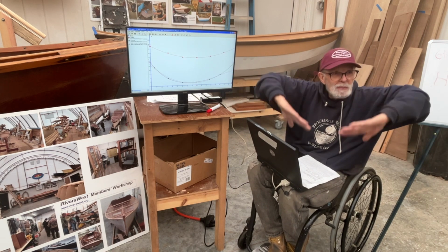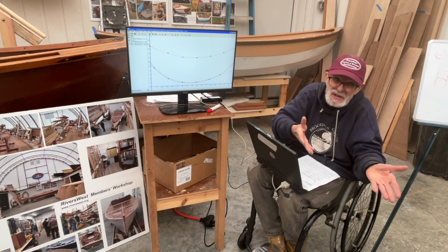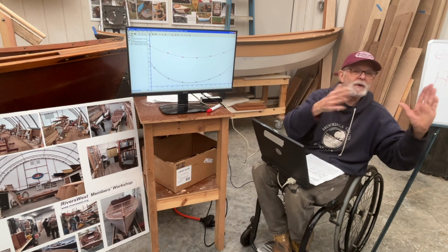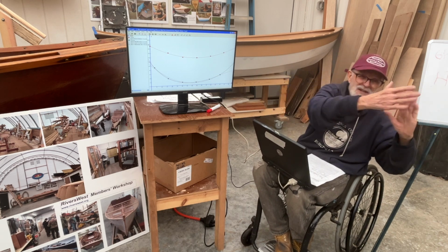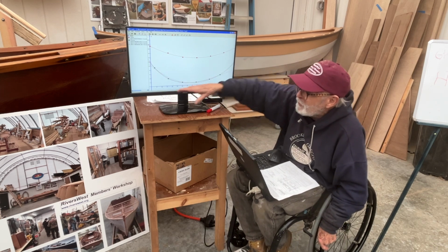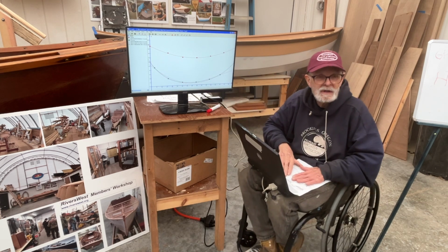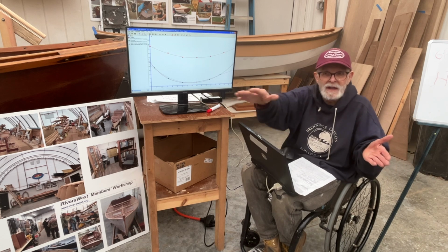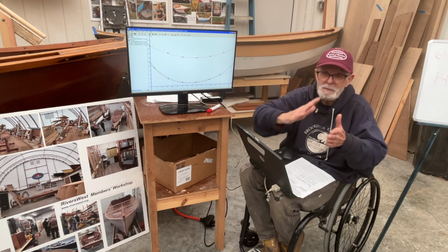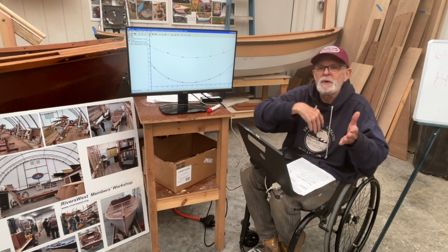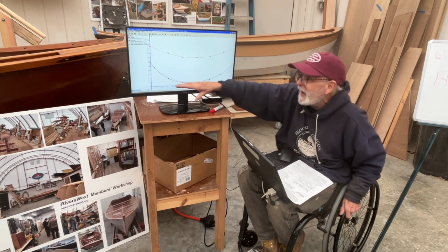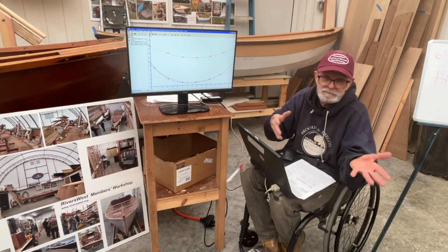How does plywood bend? I'm guessing a second order equation, a catenary curve, that's probably how it'll bend. But in fact, he wants to have a really sharp thing, because what is he doing? He's drawing a tender. He's probably going to tow the tender. He wants the bow to be really steep to ride right up over the waves. And so that's a deliberate design decision. If I were building a boat, I would flatten the thing out, because I'm not trying to tow.